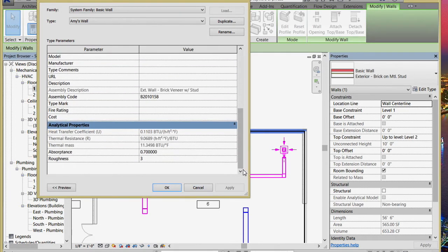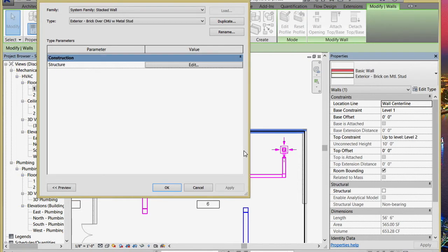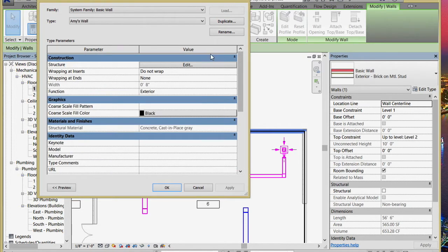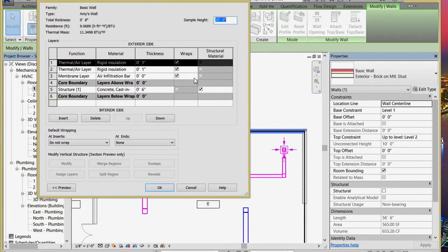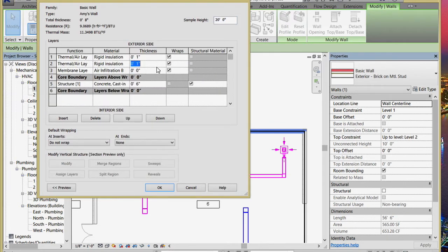Okay, so far we only got an R9 wall. For all that beautiful concrete, it's fantastic as a thermal mass, but it's not so good as an insulator. So it seems like we need more insulation. How much insulation do you think? Sure.